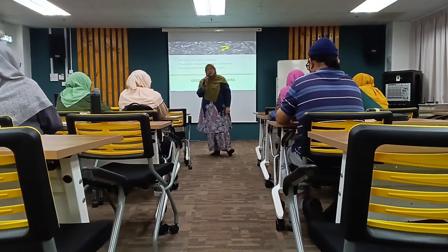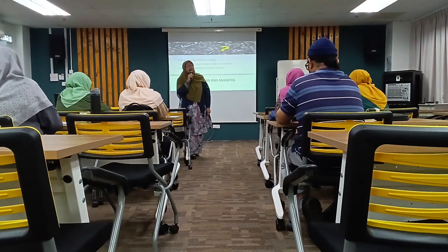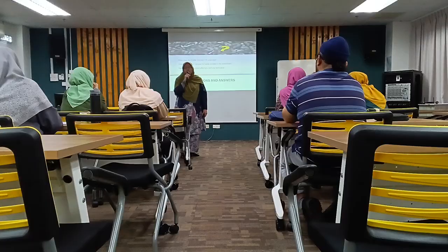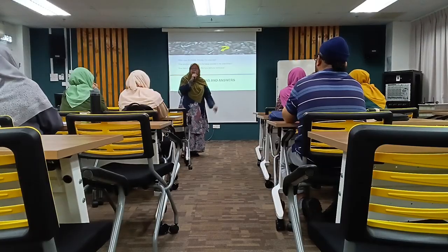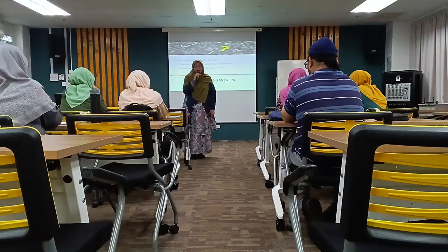The scope, which covered all the public institutions, statutory bodies. What else? The definitions to cover severity of injury. So let's say you are hospitalized after getting burned due to exposure to electric arc, for example, or high voltage, and you are hospitalized 24 hours, you are considered to have a severe injury.